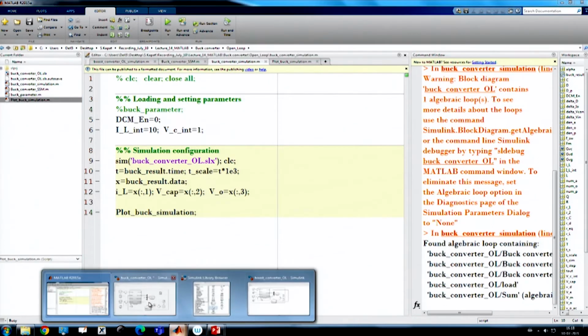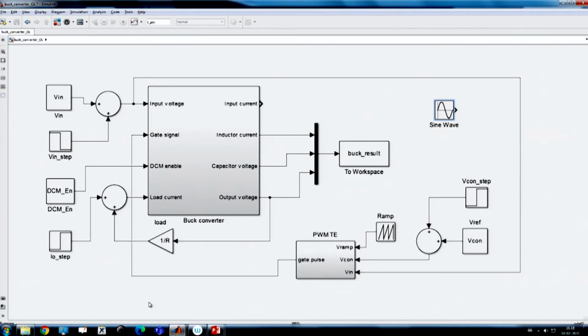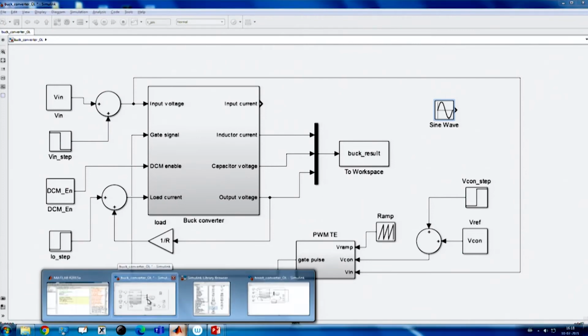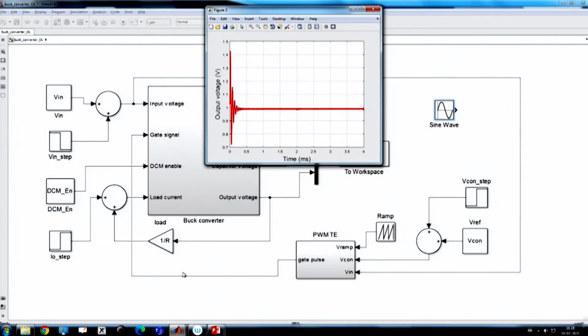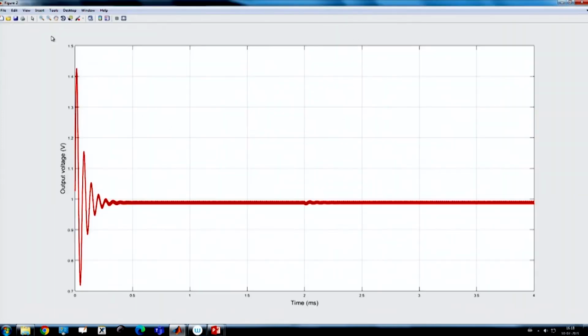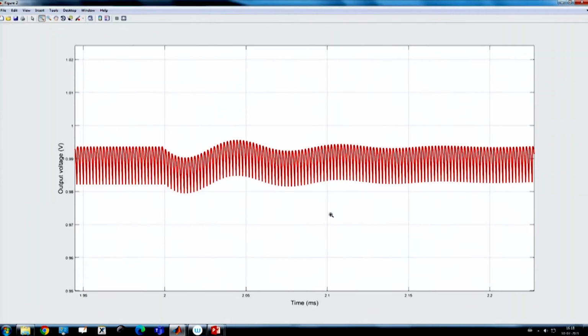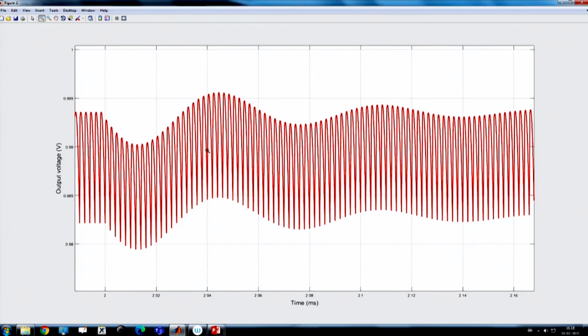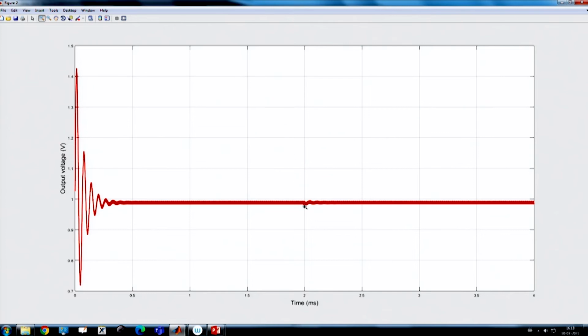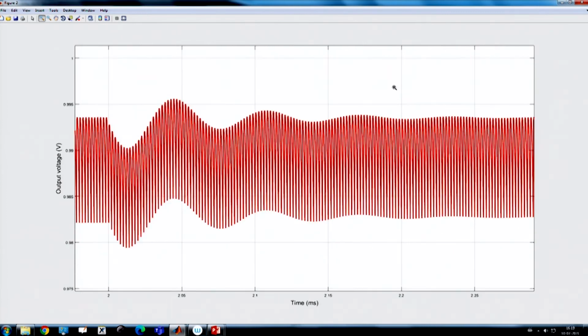Here we have applied a step transient in the input voltage, and we want to see what the response is. You see here we have applied a step transient at 2 millisecond, and again there is almost negligible impact, because the power supply has finite bandwidth, it does not have an infinite bandwidth, which we discussed in the previous class. Due to that, there is a very insignificant impact, otherwise it totally rejects the step disturbance.